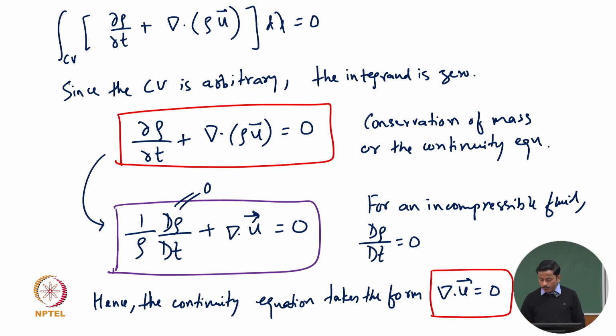There is something that we can infer from here: the conservation of mass for an incompressible fluid puts a restriction on what velocity fields can appear in the system. As you can see, this means that the divergence of the velocity is 0. That is, there cannot be arbitrary sources or sinks in the fluid, and this comes from the fact that the fluid itself should conserve mass.